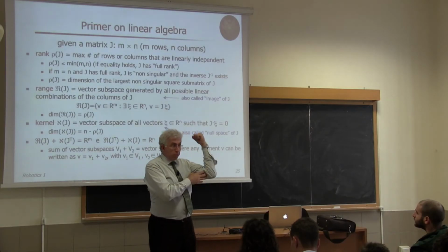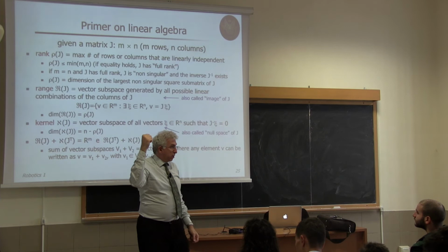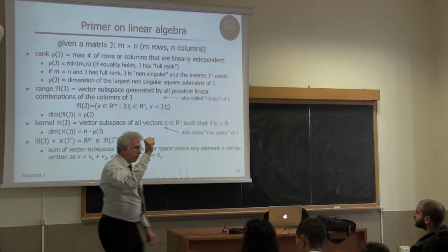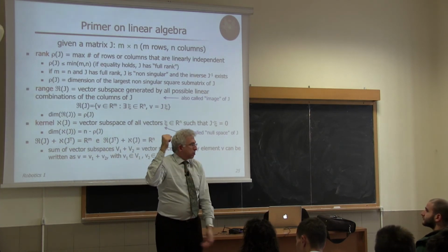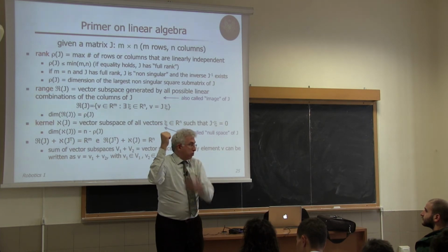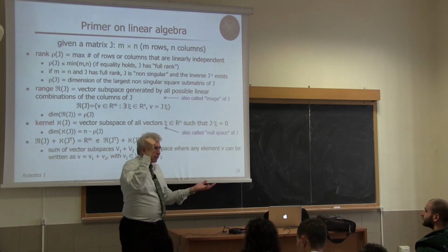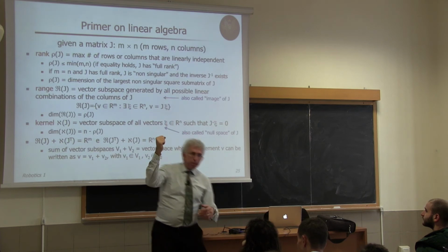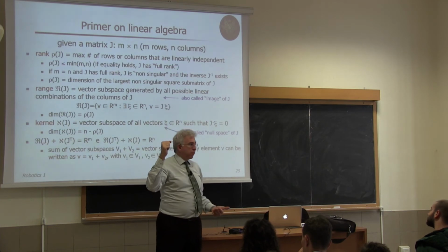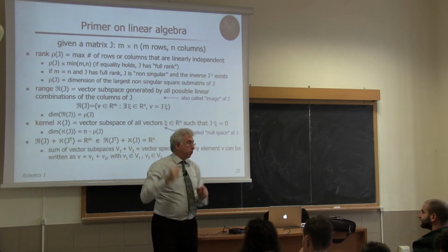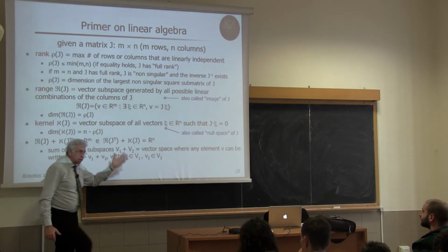So if you have some joint motion, for instance, my arm, which is highly redundant, if I'm looking at the end effector velocity and I'm doing this motion, okay, I'm moving my joints, but I'm not moving the end effector, which means that my vector of joint velocity is in the null space of the Jacobian of this mapping. So if I have some instantaneous velocity which does not move this, and some other velocity that does not move this, if I combine them, I will generate a new velocity vector in the joint space that will not move the end effector. This means being a vector subspace. Okay? So you have these properties.